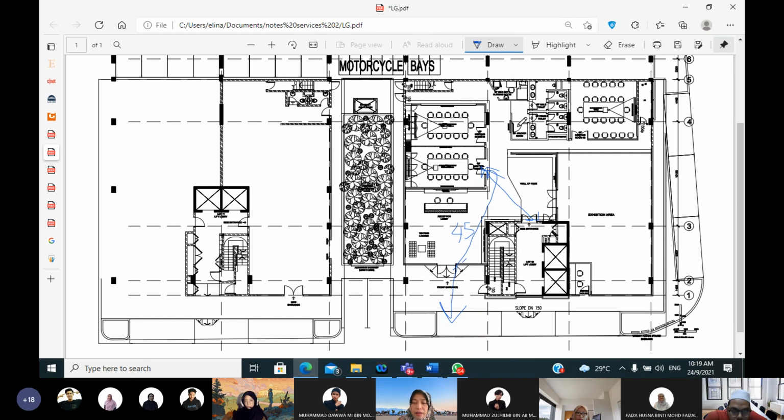Okay, let's say this is another room here. You cannot cross like this to calculate. Cannot. So we call it as a perimeter. When you want to calculate 45 meters, you have to calculate as if the route of the people, like this. Okay, this is a perimeter. Calculate from here to here how many meters, from here to here, until exit door.